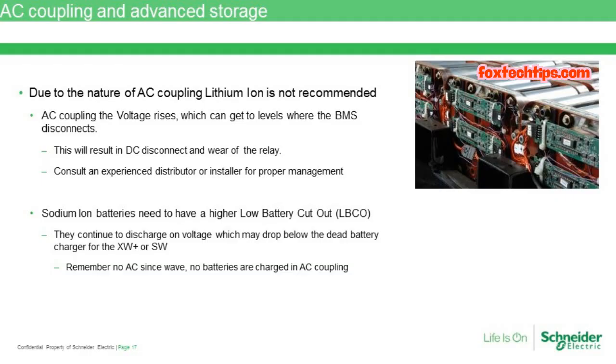And so when sizing those batteries, even if the recommendation is, oh, don't go below 50% depth of discharge, what I'm arguing is that the batteries will actually age out before they cycle out, even if we did a depth of discharge of 100%.